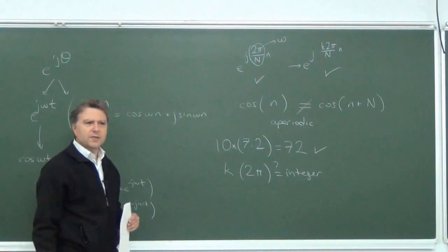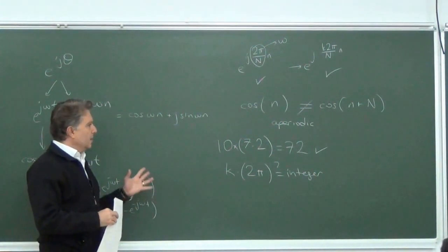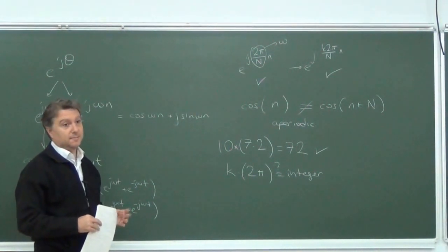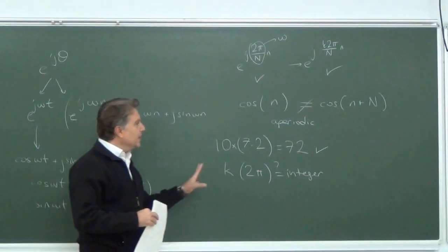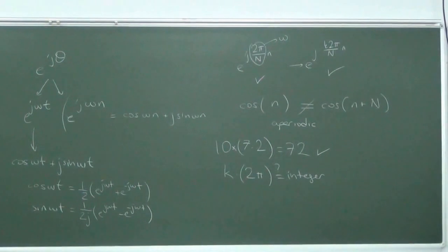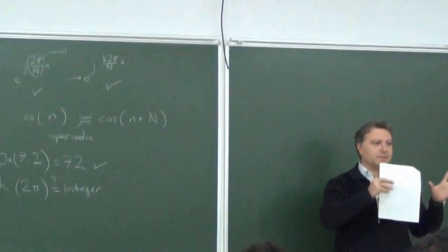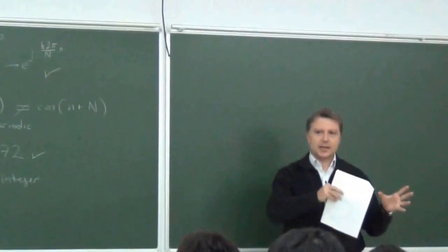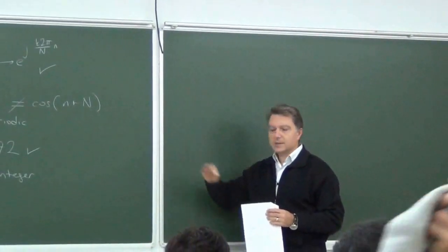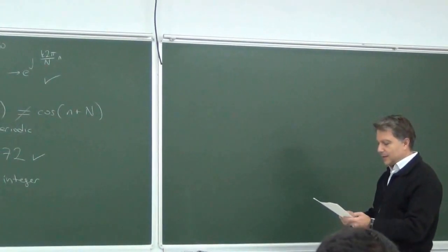All right. So be careful about the periodicity definitions of discrete time sinusoids or discrete time periodic signals, so-called. Without being periodic, you shouldn't start the analysis with that assumption. So first you must check whether it's periodic or not. Periodic signals will have their own characteristics and analysis methods, tools. The others, non-periodic ones, will have different tools. Okay, so let's not forget about that.